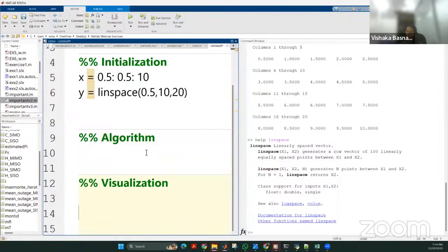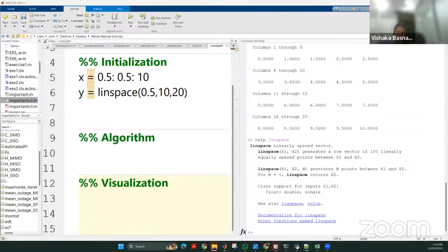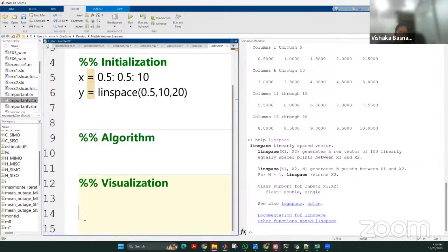One thing to note is that older, or previous, versions of MATLAB had this feature where we needed to define the function in a separate file. However, as of now, the functions can be defined in the same file itself, at the bottom of the file.